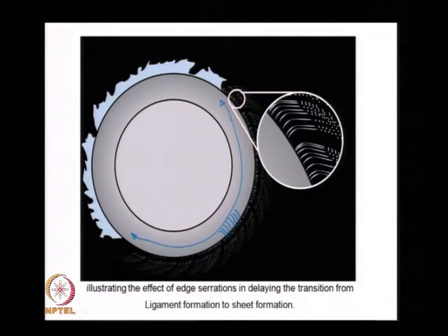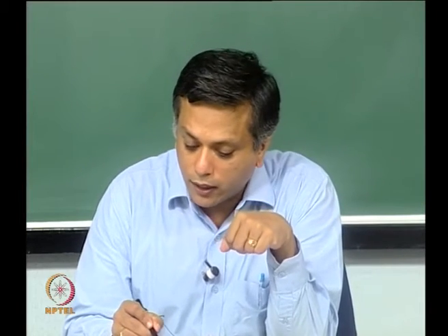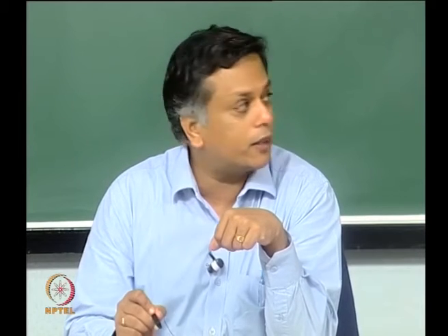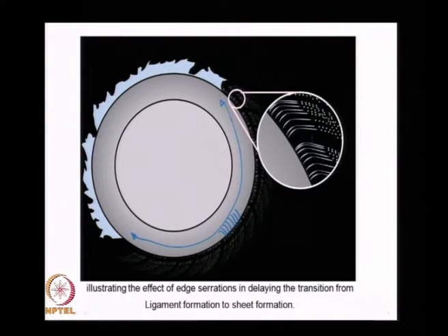Okay, when I put those grooves, what I end up doing is the liquid flows only through those grooves as it spills over the cup, and each of the liquid that is spilling in through one groove is like a little jet that breaks up into drops. Now, the size of the drops are comparable to the size of the liquid jet. So, this diameter d there. So, essentially by controlling the diameter or the depth or the width of the grooves, I can control the drop size.